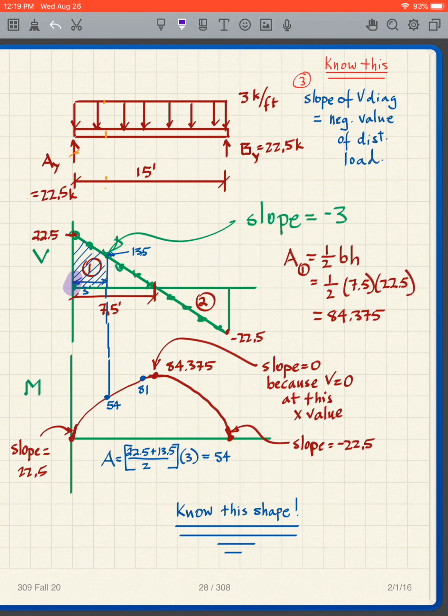It just takes time. If we made 10, 15 cuts and calculated out the shear and bending moment at each location, we can get our shear and bending moment diagram. But the faster way to do it is the shortcut method. I start at 0 with my shear diagram, and this says go up 22.5, so I go up 22.5.